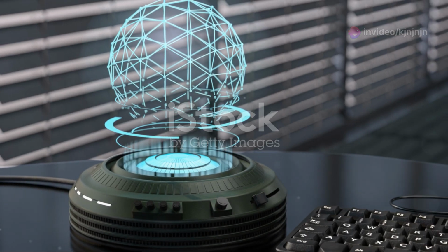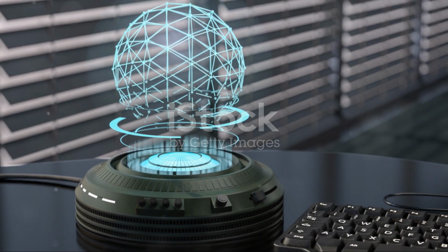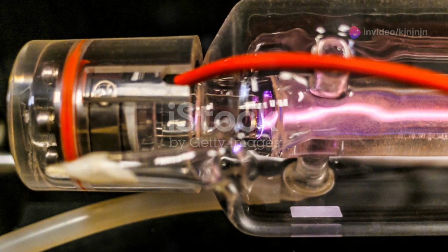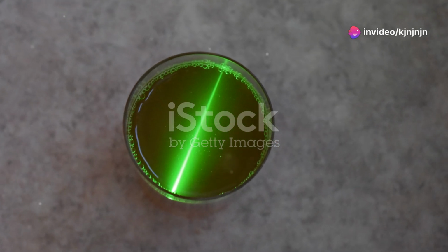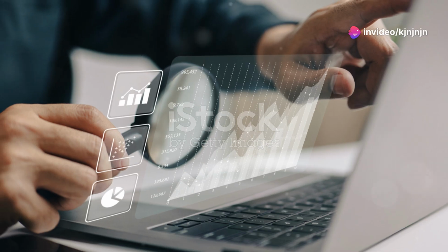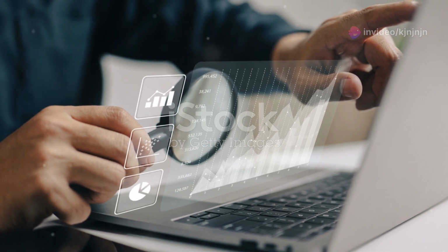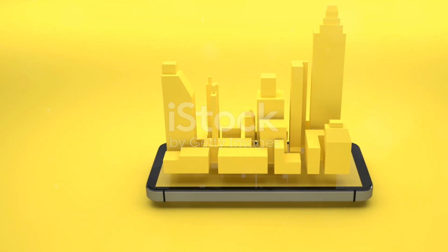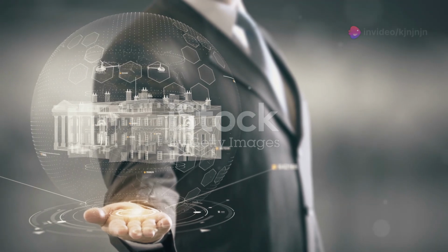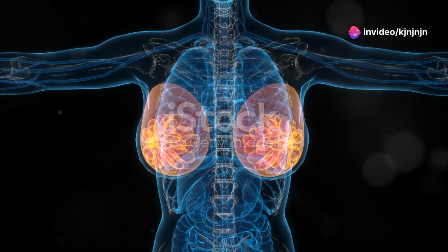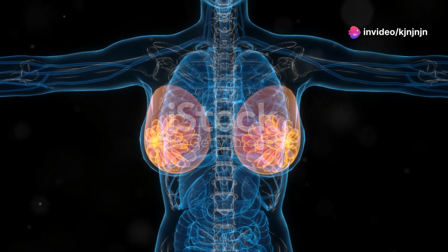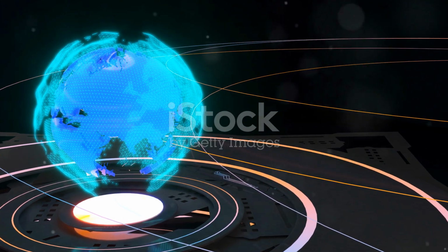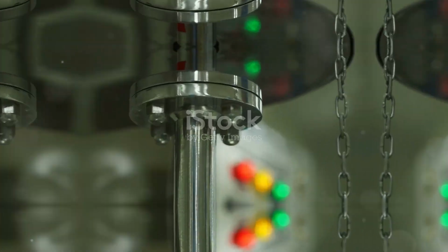Holography is an optical NDT method that creates three-dimensional images of objects. A laser beam is split into two beams, one illuminating the object and the other serving as a reference. The interference pattern between the two beams is recorded on a holographic plate. When the plate is illuminated with the reference beam, a three-dimensional image of the object is reconstructed. Holography can be used to detect subtle surface displacements and deformations, making it suitable for strain measurement and flaw detection.